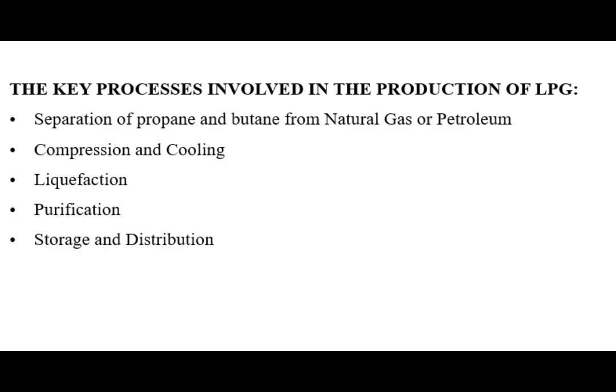7.2.1.2 Compression and cooling. The separated propane and butane are then compressed and cooled to facilitate liquefaction. This process exploits the real gas behavior of these hydrocarbons, where increased pressure and decreased temperature cause them to deviate from ideal gas behavior and eventually liquefy.